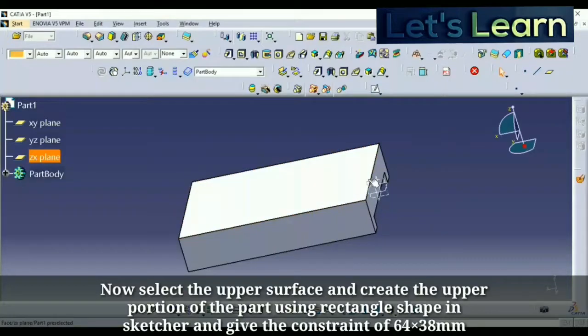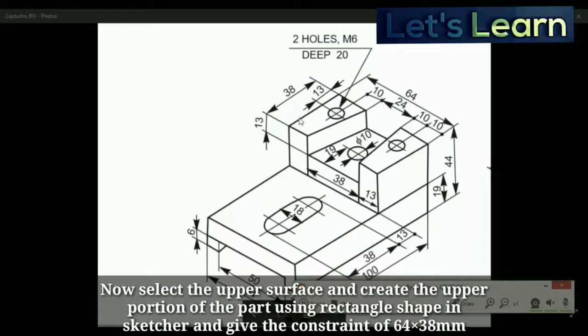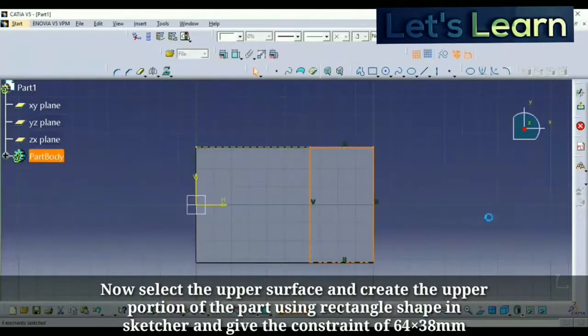And now I'm going to draw another sketch over that surface, the top surface. So this is the top view. I'm going to draw that upper part and pad it. Now let's see how we can draw it. First project this part's lines and make them construction so that they won't intersect our part. Then draw a rectangle and match the points, and now give the constraints to that part.